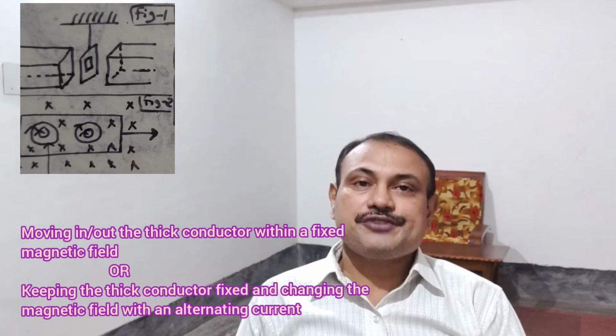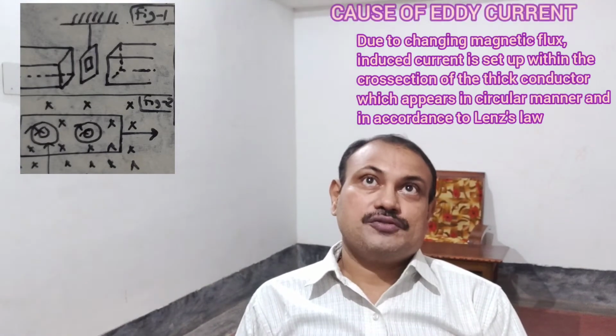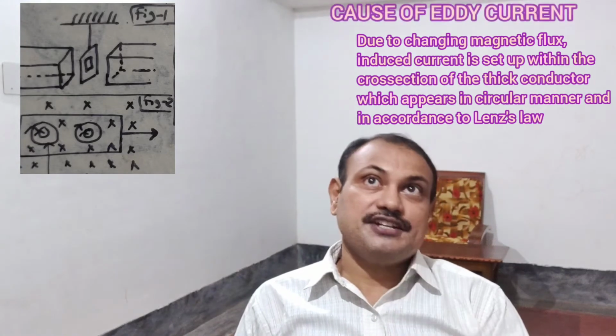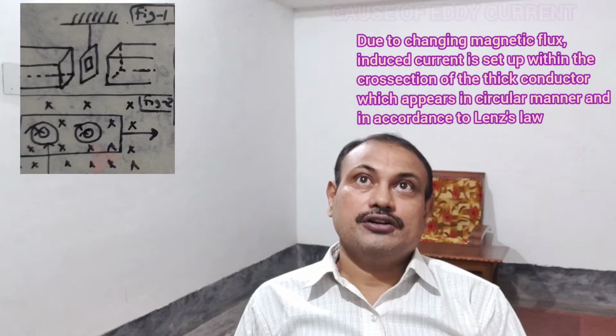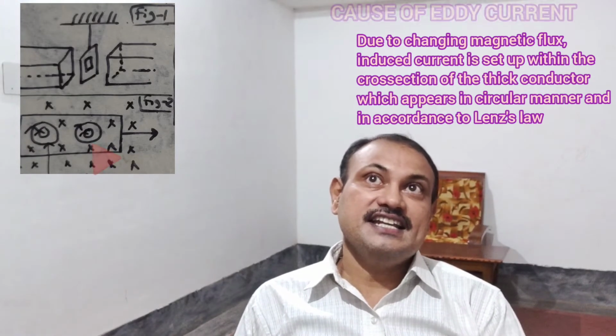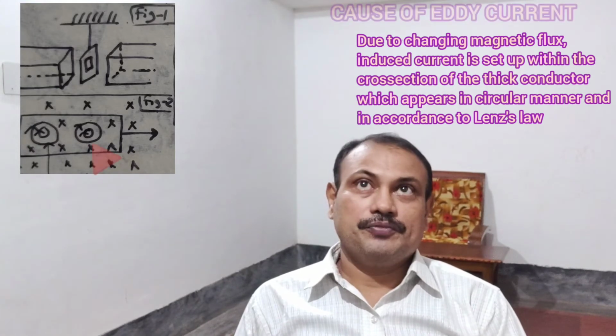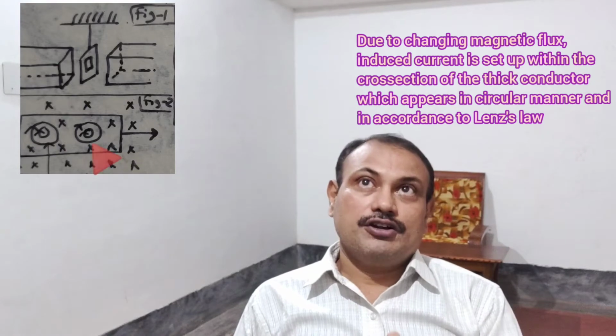Now, what is the cause actually of this eddy current? If you see the picture, due to changing magnetic flux, induced current is set up within the cross section of the thick conductor, which is in a circular manner, and it is in accordance with Lenz's law. It is in the cross sectional manner. It is because the conductor has to be a very thick one.